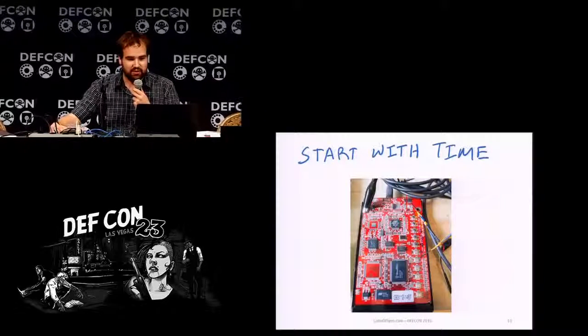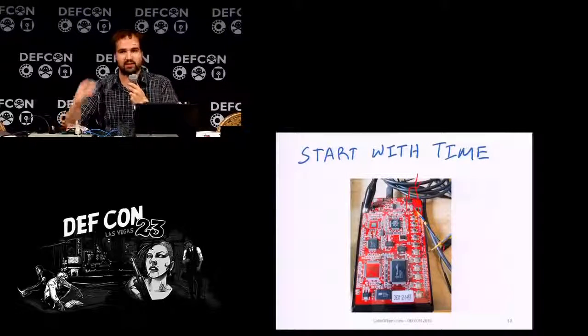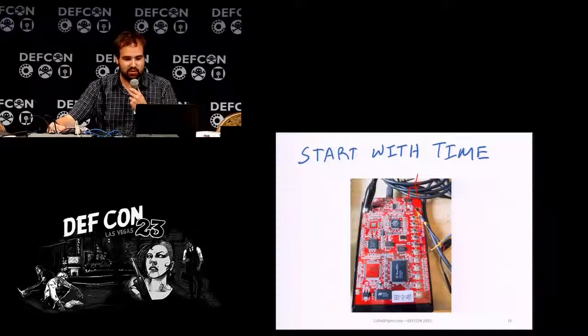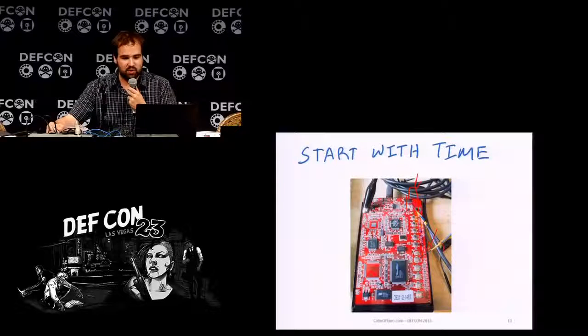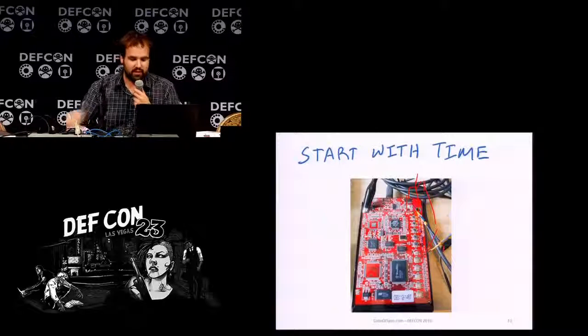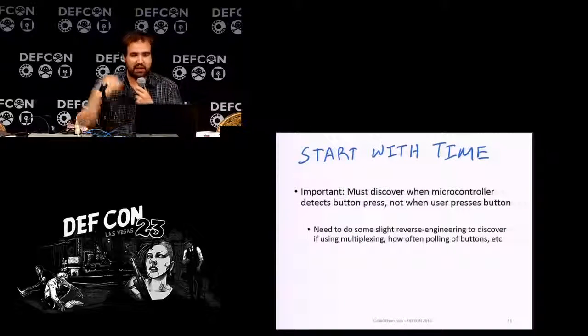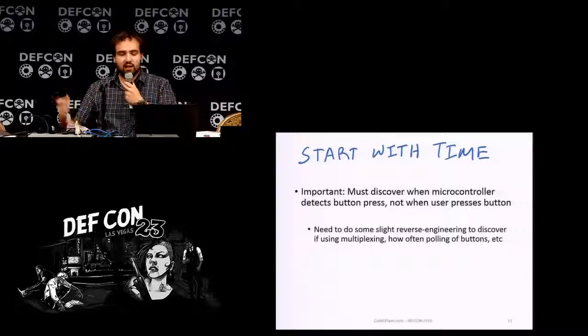One at the top here is just probing. There's an LED that says your password was wrong, and there's another one that's just connected to one of the buttons. Down here you can sort of see, sorry it's in red on red, but what we're trying to see is the time delay between when we put in the last digit of the PIN, when it starts the comparison, and when that LED goes on.